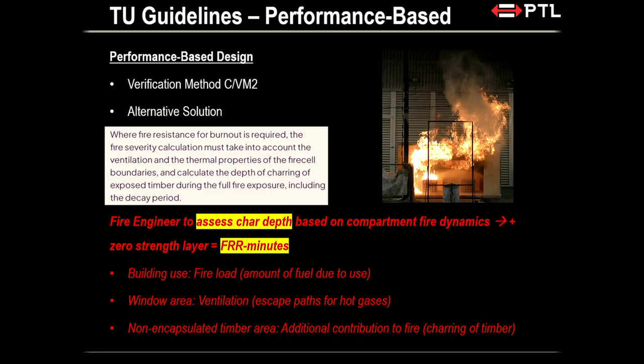So in this particular case, I would calculate the char depth. This is the difference from the previous methodology. In the previous methodology, your fire resistant rating is already there. It's already there for you to use. You multiply by the standard charring rate, you'll be done. But here, I have to do a char depth calculation.